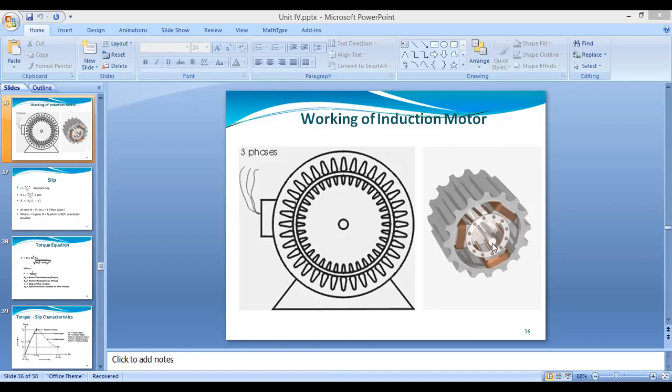What we are doing here, we are supposed to study about the working principle of the induction motor. When we are studying about the induction motor in our syllabus, we are supposed to study only the three-phase one. We are using three phase by using the R, Y and B phase sequence. So when we are giving the phase sequence of the current, that is R, Y, B, the resultant MMF is nothing but the force that will move from the axis of the leading phase to that of the lagging phase.